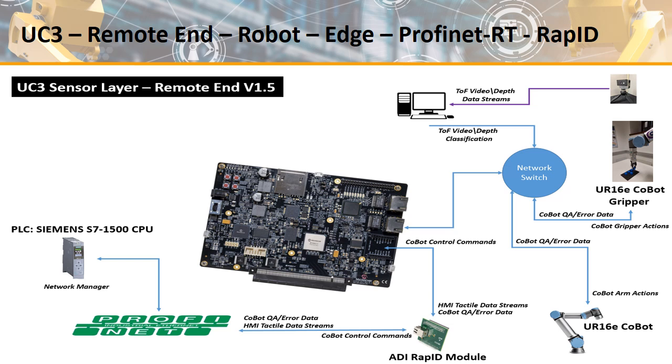Next, we look at the remote end of the platform, and I don't have to spend as much time. I've talked about the Profinet, and the data is transferred across the Profinet, and you can see here there are Cobot control commands. Cobot stands for collaborative robot. The Cobot control commands are received by the edge components, whether it's a Microchip PolarFire, or the STM32 type of edge devices, or indeed other future edge devices could be built into this platform as edge components are constantly evolving.